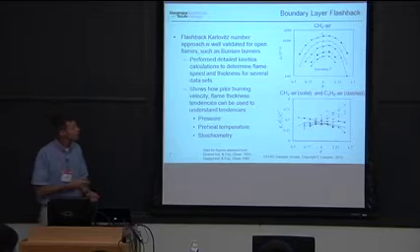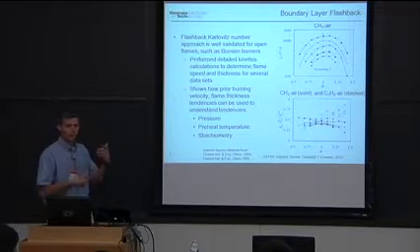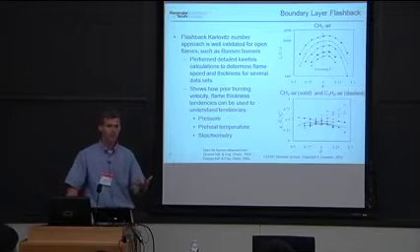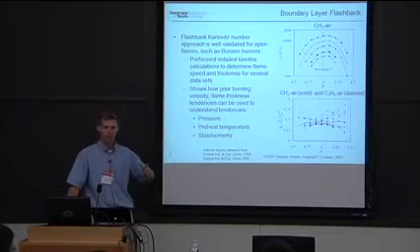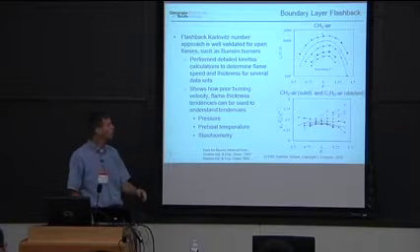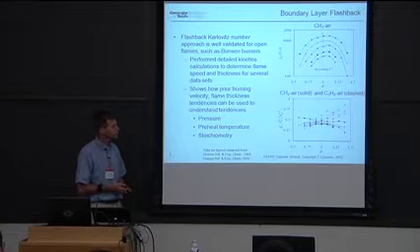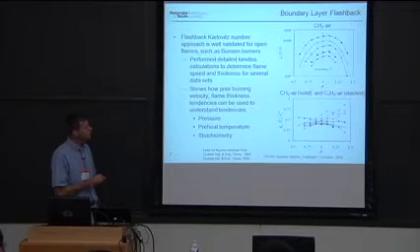As we increase preheat temperature, you can see that the critical velocity gradient blasts up because the flame speed is exponentially sensitive to temperature. So as your preheat temperature goes up, you've got to have more and more of a velocity gradient. You have to have basically a higher and higher velocity core flow to keep the flame from flashing back. So this is all that data in dimensional form.